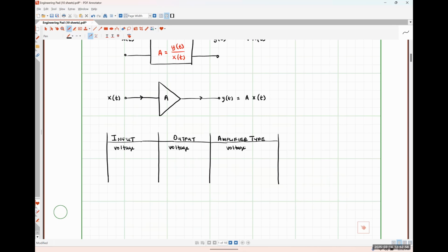So every single one of us actually has a voltage amplifier in our pocket or sitting on our desk, in the case of Connor, because his phone is not in his pocket. We all have voltage amplifiers in our phones because that's what's picking up the telephony signals. And then it's going into a power amplifier to be able to actually drive the speaker that we hear the phone call with. And again, any type of audio amplification is usually going to involve a voltage amplifier preamp stage and then a power amplifier secondary stage in order to drive the speakers, okay?